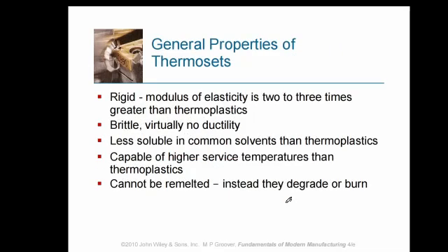And the thermosets are very rigid. The modulus of elasticity is 2 or 3 times greater than for thermoplastics, which means they are less elastic, very rigid. They are brittle, which means if you try to bend them, they break, and they exhibit virtually no ductility. You cannot stretch them to increase their length.